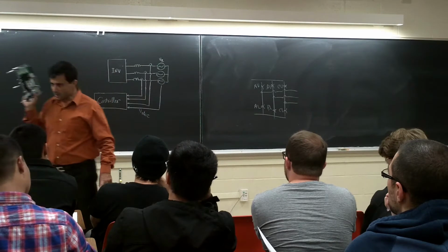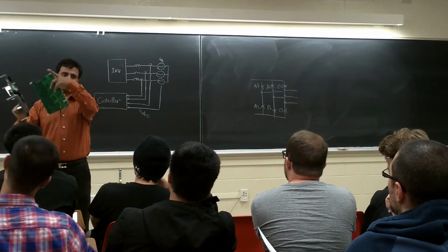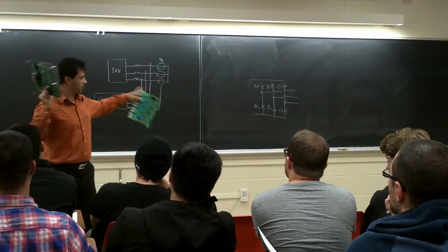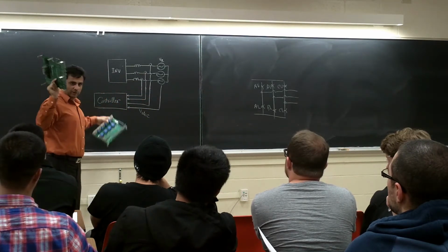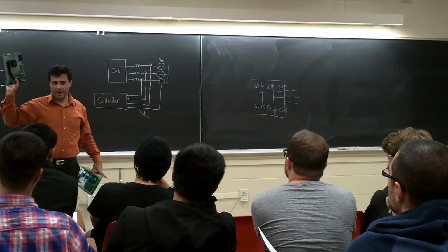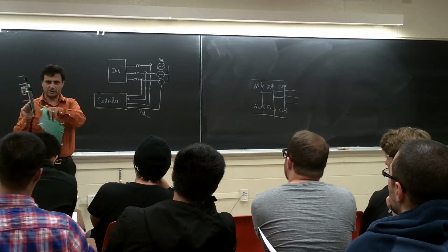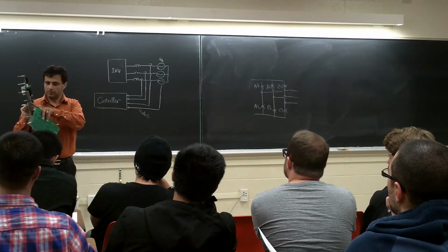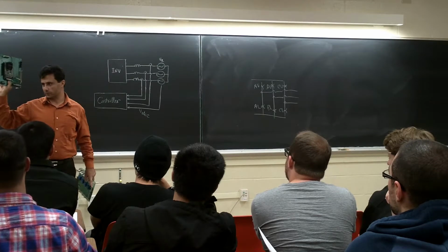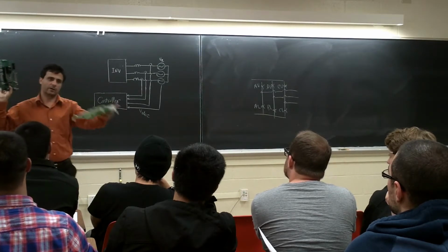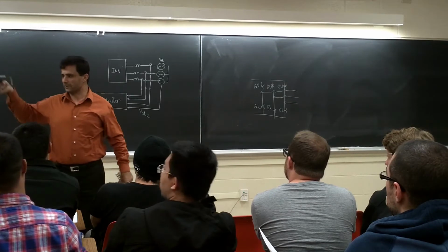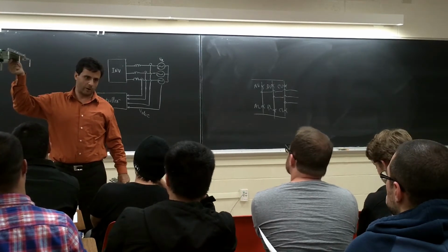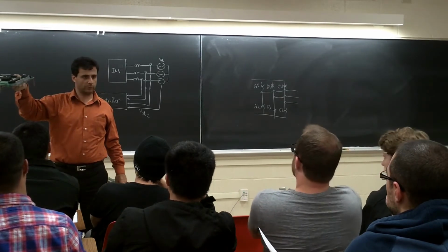So what is happening is the DSP does all the calculation, all the crazy things. This is the control box right here. It does all those calculations, and after that, it generates the PWM signals through these gray connectors. This one will be connected to that inverter. So basically, my control board is completely separated from my power board, right?